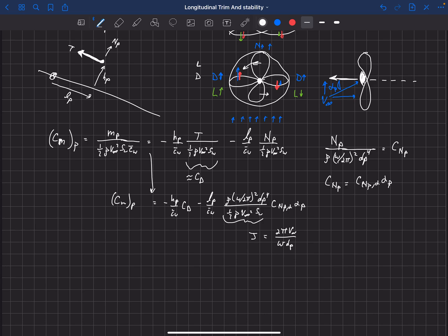Another thing that we want to look at is the angle of attack of the propeller. That is going to be equal to our free stream angle of attack, if we've aligned, remember, this fuselage reference line with the direction of thrust. That's not a hard requirement. Actually, we're going to include a term here that will relax that a little bit. So we're going to have our free stream angle plus a mounting angle alpha naught P, if we wanted to mount that propeller at a different angle to that fuselage reference line, and then we'd have minus epsilon_P.